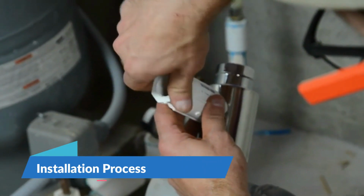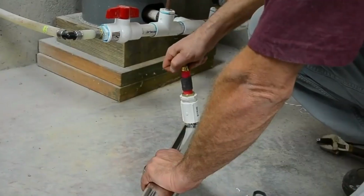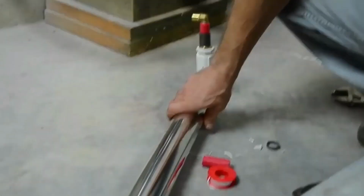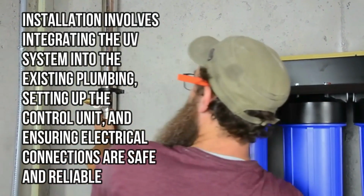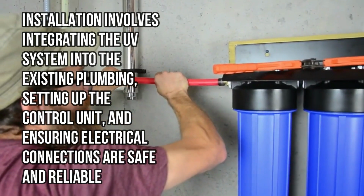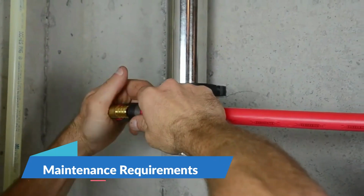exposure. Installation process. Location. The system is usually installed at the point where the main water line enters the home, ensuring that all water used within the house is treated. Setup. Installation involves integrating the UV system into the existing plumbing, setting up the control unit, and ensuring electrical connections are safe and reliable. Maintenance requirements.